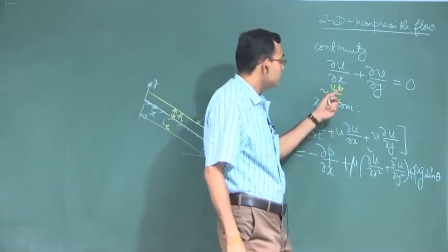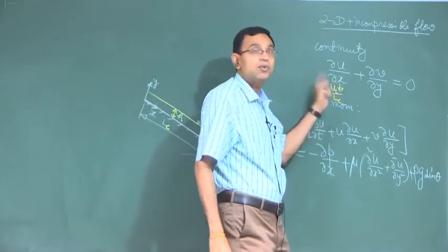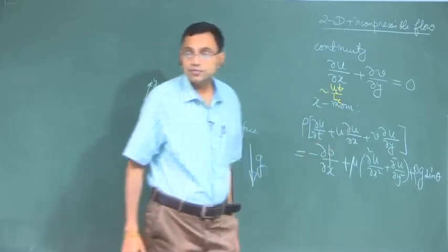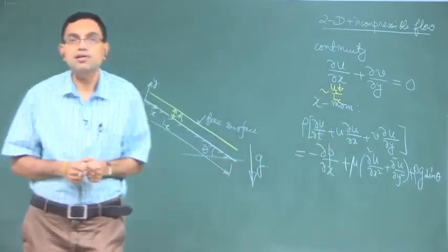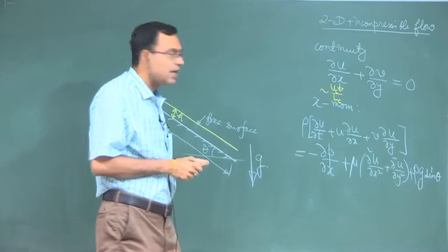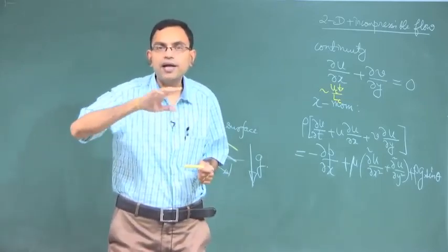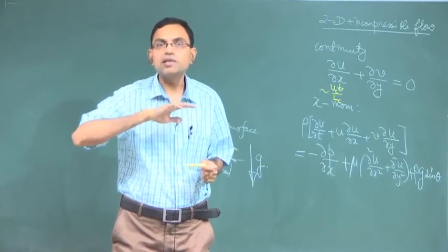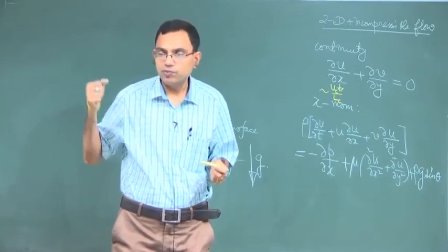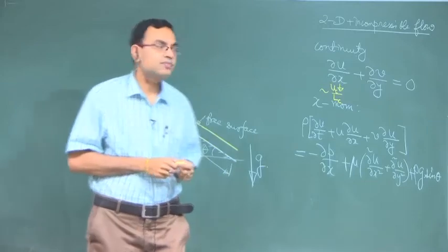So, the question, and a very important question, is what is Uc, right? What is the characteristic velocity? In a boundary layer over a flat plate, you already have a predefined characteristic velocity which is u infinity, the fluid which is coming from the free stream.